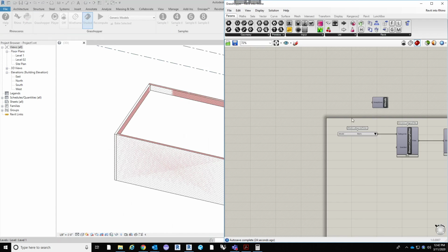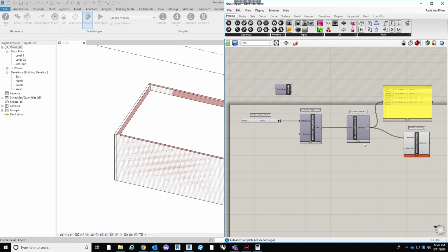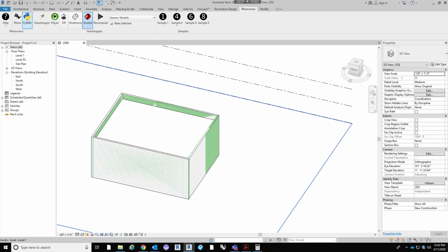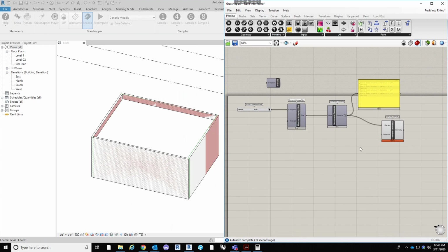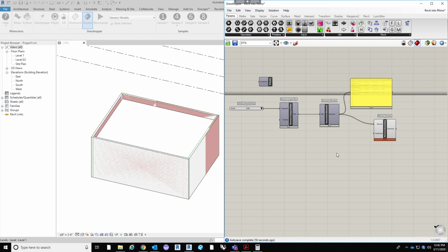Okay, and then when it went back into my Grasshopper script, it's all the same, and it still has that geometry. Now that geometry is actually populating. Revit does not like complex curvature, and Rhino.Inside hasn't figured out a way to deal with that yet. I'm sure once they continue to develop this software, it will get better and better. But for right now, let's just do 4 straightforward walls.